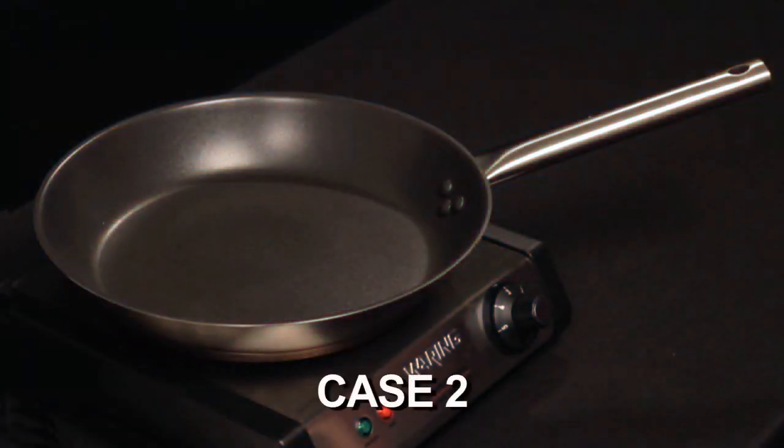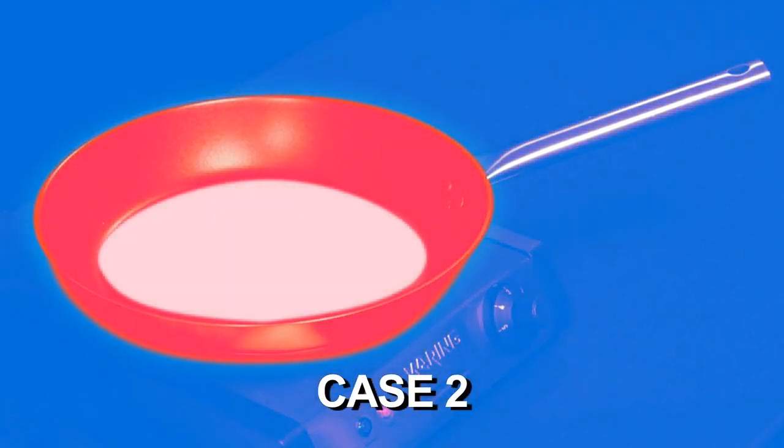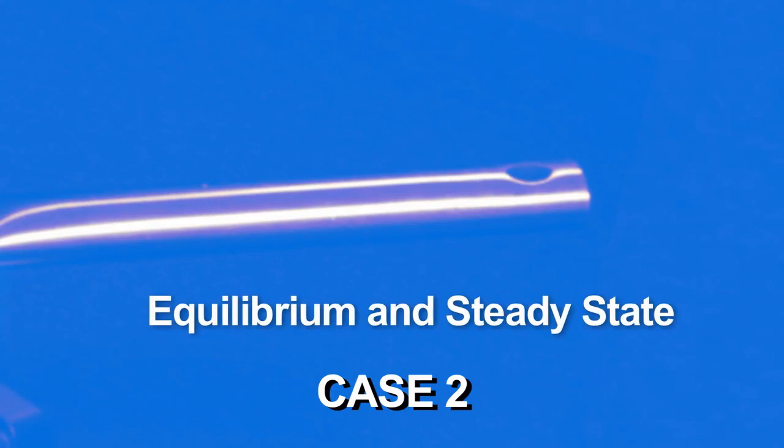Now let's consider the opposite case. What would happen if the handle were completely insulated from the pan? The handle would be at thermal equilibrium with the room, and would stay that way no matter how hot the pan got. The temperature of the handle would be exactly the same as that of the air. Just as in our first case, both the heat flow from the pan to the handle and from the handle to the air are zero and constant. Thus, this case of thermal equilibrium is really just a limiting case of steady-state temperature, except, of course, the handle will be cool enough to hold.